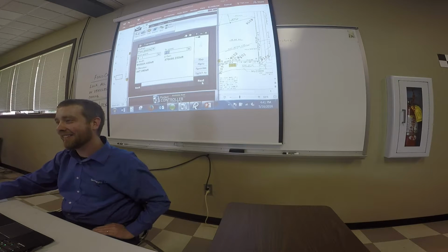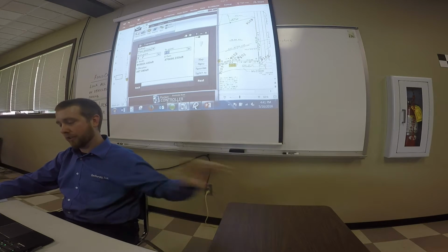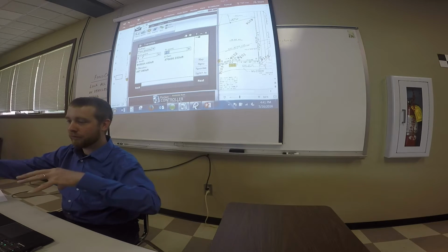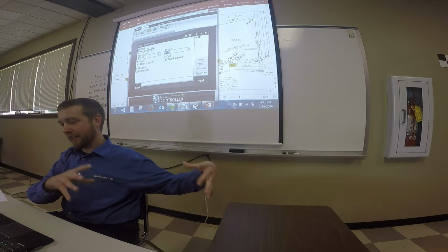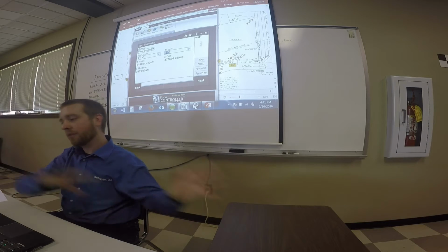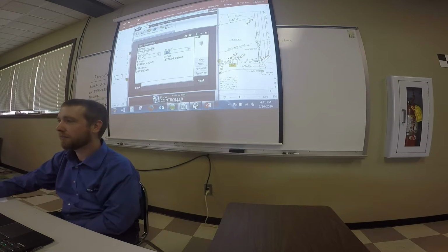To be clear, if you had from 103 to 9101, that's going to move the point you shot, which you don't want. The from point is where it's coming from, the 2 points is where it's going to. So you want to take your plat from the assumed datum to your datum. Transform means move.